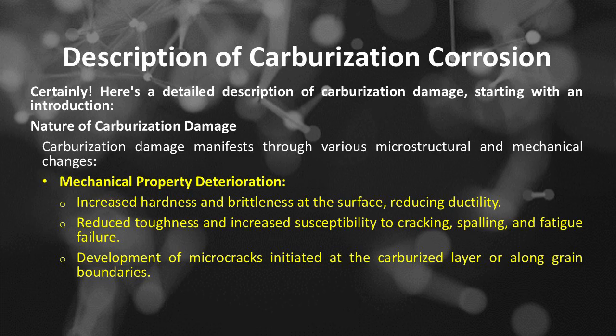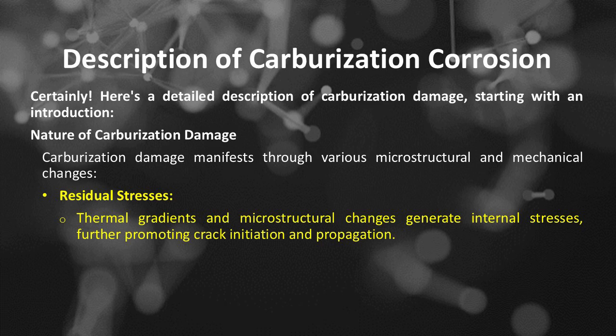Mechanical property deterioration: increased hardness and brittleness at the surface, reducing ductility; reduced toughness and increased susceptibility to cracking, spalling, and fatigue failure; development of microcracks initiated at the carburized layer or along grain boundaries. Residual stresses: thermal gradients and microstructural changes generate internal stresses, further promoting crack initiation and propagation.